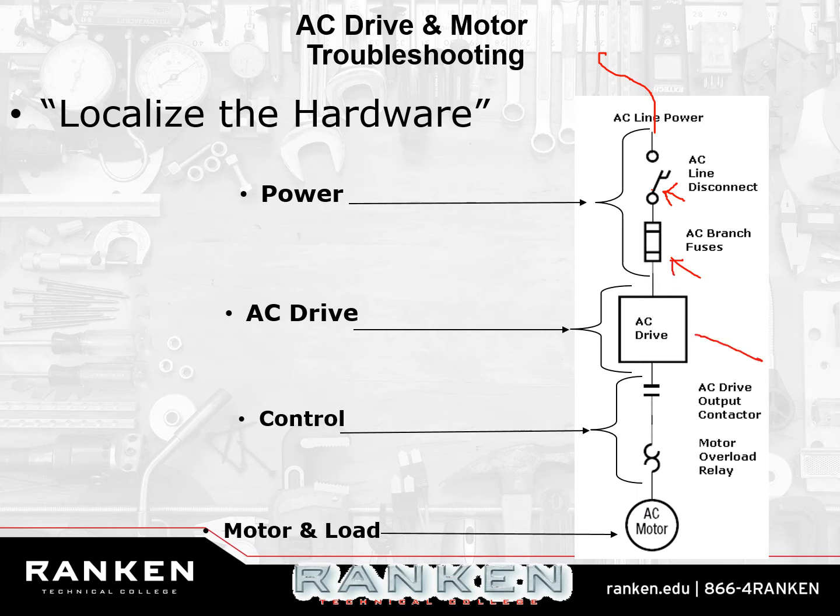And you start with the simplest thing first. Is the disconnect arm closed? Well, yes, probably. But let's go check it. Are the fuses good? Yes. The AC drive? Well, something's going on there. We'll check the codes. We'll do some stuff. The AC drive output contactor. Usually, like I said, this is internal. But this will be based on